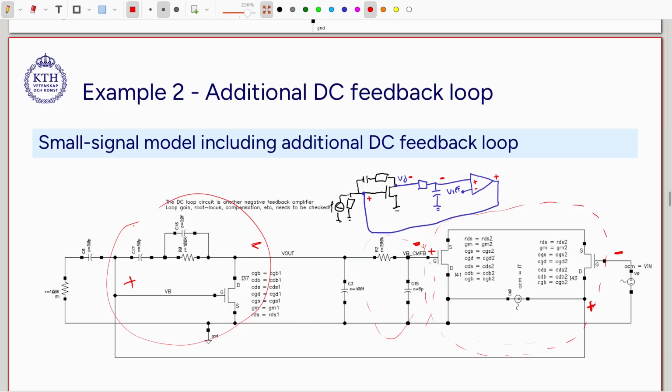So the advantage here is that we are normally just concentrated on making sure that the DC is set to the right voltage, so it is only low frequencies that are relevant for us. So we have fewer concerns of stability problems at very high frequencies, because we just cut the gain at high frequencies, and for that we have this low pass filter.